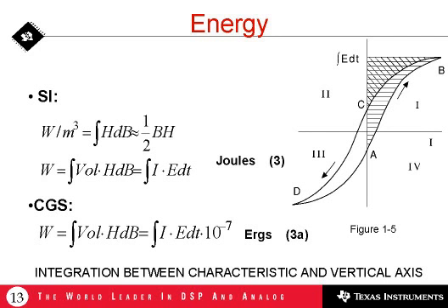If we start at point A on the hysteresis loop, and notice that the vertical axis is characterized as volts-seconds and the horizontal axis by current. In other words, we're just thinking of this in electrical terms to make it simple, but realize that underlying volts-seconds is flux density and underlying current is field intensity. As we start at point A, there is no energy whatsoever stored in the core. As we move from A toward B, the area between that characteristic and the vertical axis represents energy.